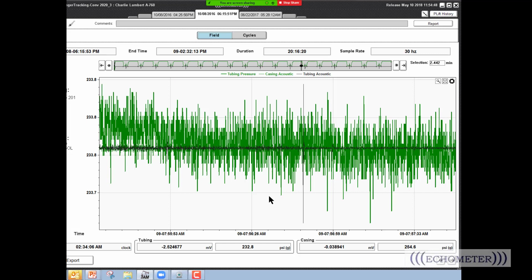And so you can. We've written a paper on finding washed out valves and bad check valves on gas lift wells with two gas guns. You shoot one gun and listen on the other at the exact same time, and the valves that leak will pass the pressure wave through, and you'll hear it on the other pipe.